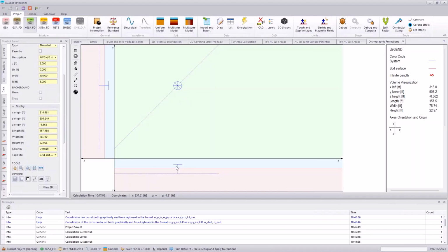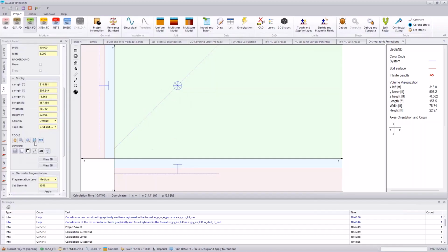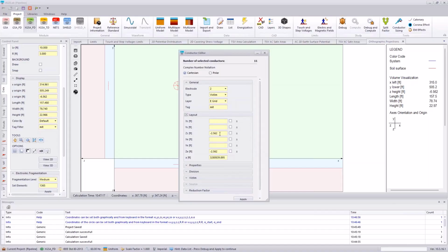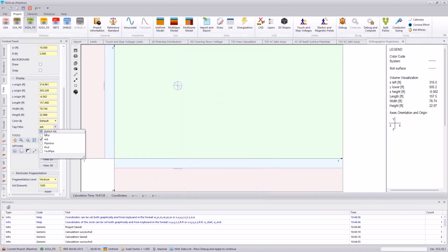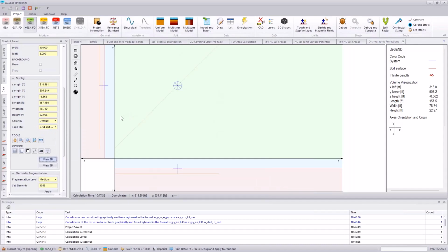You can see on the XZ view, when I snapped, it actually snapped to the top of that appurtenance or the top of that pipe. Let's go ahead and shift that down. I want that to actually go down to, say, 6 inches. So I'll just manually force that value into the earth. And now we've put in one test station, or one mitigation strategy for one of our test stations.